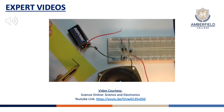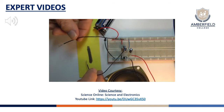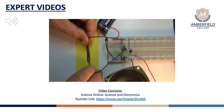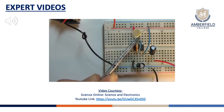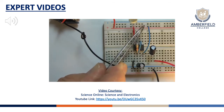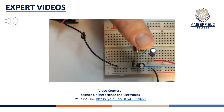Pencil lead is often made from graphite. We can use graphite to create a resistor. Draw a heavy pencil line, then replace R2 with 2 wires. Sliding the ends of the wires across the pencil line creates a wide range of frequencies. There are also resistors available that vary with light. You can use an LDR, a light-dependent resistor, in place of R2. Use your hand to block the light falling on the LDR. Sounds like this.